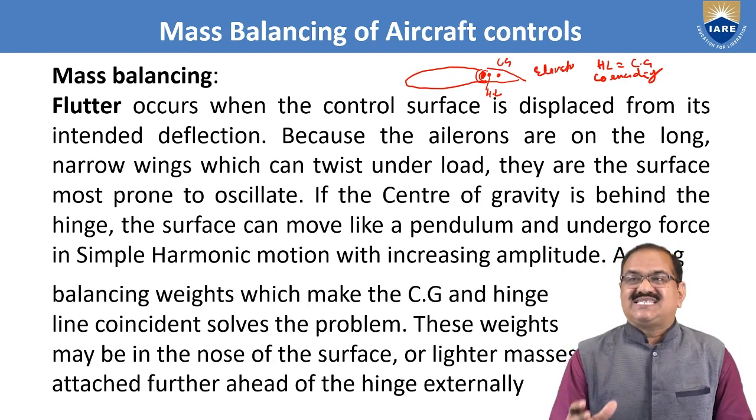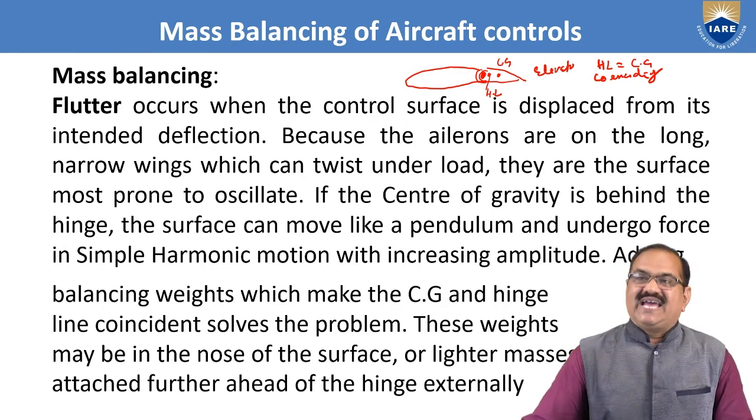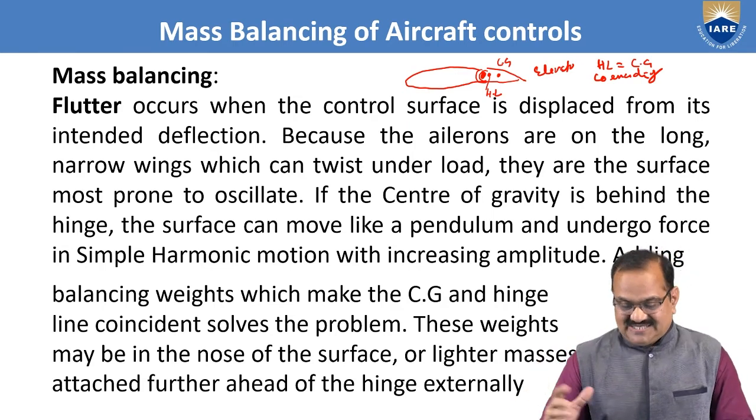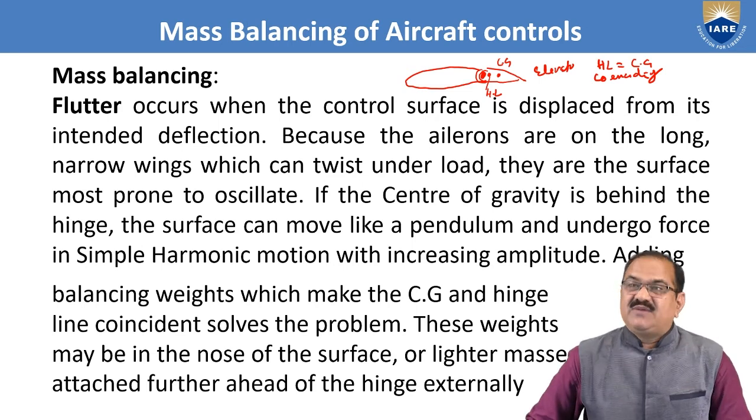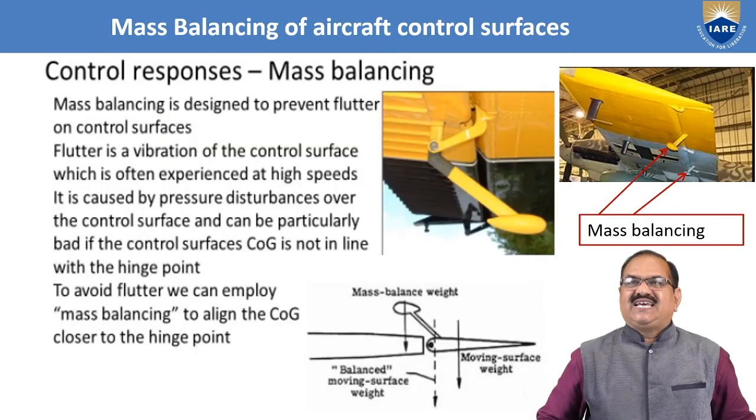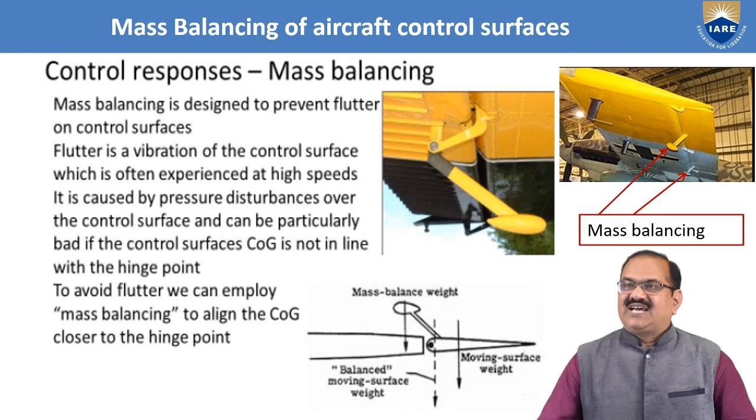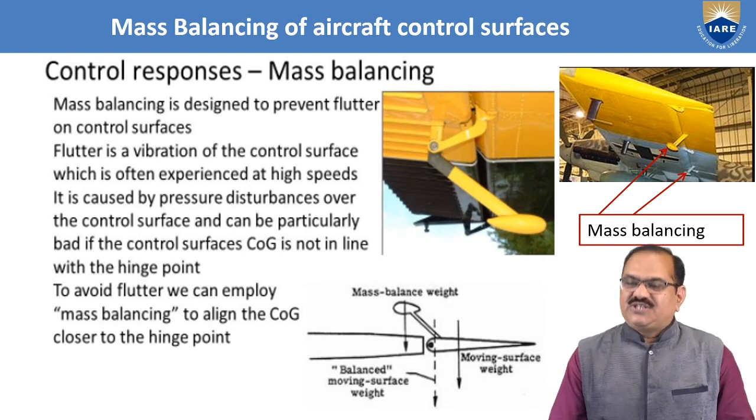So it is very much essential that from time to time during aircraft maintenance, we have to see that the aircraft controls are balanced. Balancing is very important for this. You can see here how this mass balancing is done.